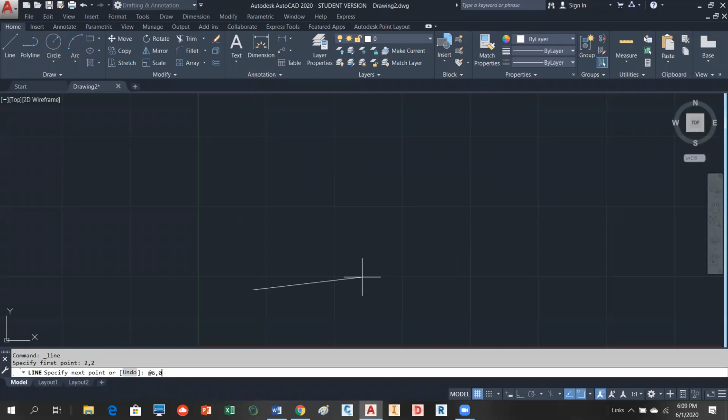No questions? Okay, so if you hit the @6,0, what you'll notice when we hit enter is it does the same thing as the last input, but we had to actually do the math. We had to add it, subtract it, and we don't have to do that if we're using this. So this makes it a little bit simpler. In fact, it's a very, very nice way of working when you're dealing with coordinates. Okay? Any questions?